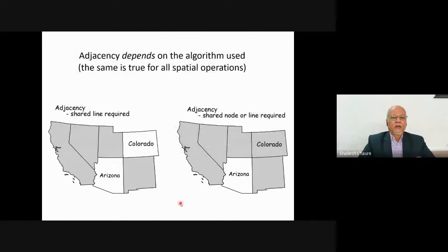Now, I may be interested in finding the adjacent polygons. Adjacency, I can inquire. So I select one feature on the map, and then I try to find out, suppose I have a district map of Madhya Pradesh, and I click on any of the districts, and I inquire the system how many districts are touching this particular district. You may wonder why we need it, but when we automate things, many a times this kind of thing is needed, because human intervention will not be needed.